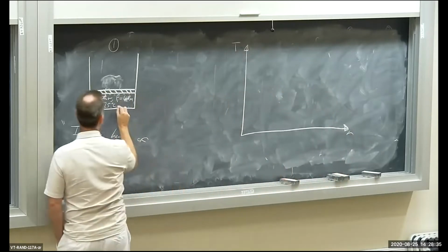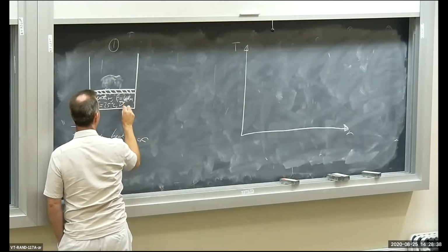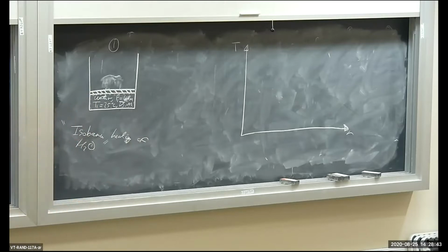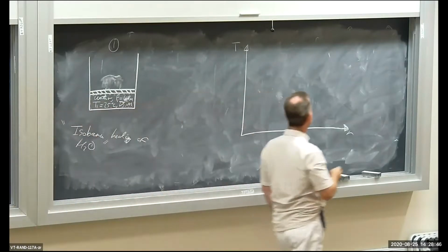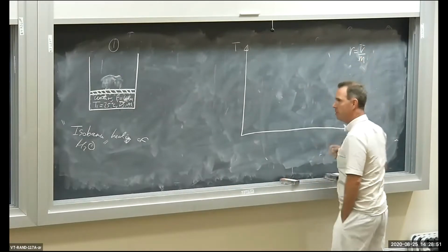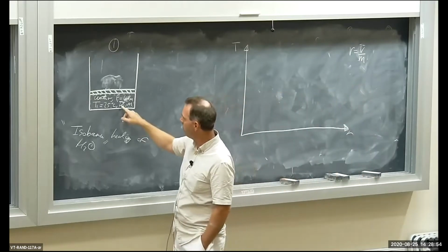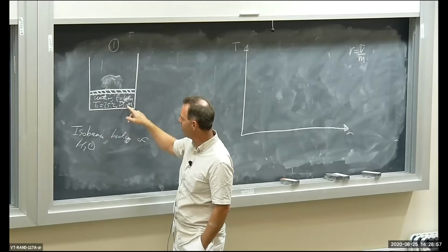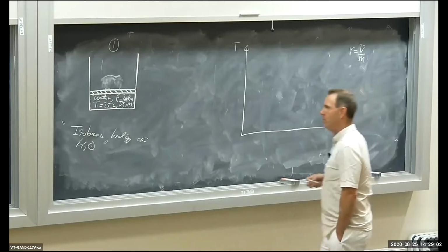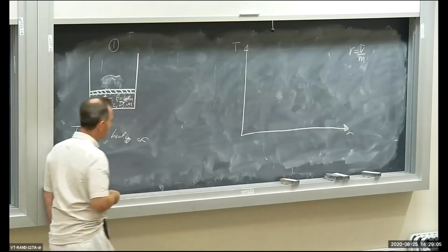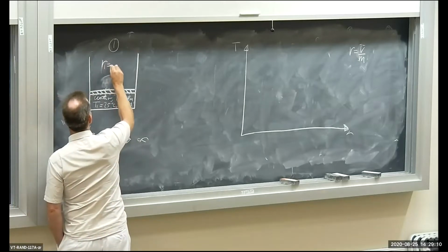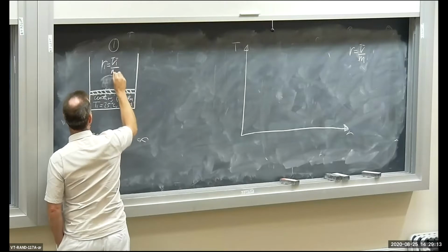So this thing originally has some volume V1 and a certain amount of mass inside. Remember, specific volume is volume divided by the mass of the system. So I have an initial volume, state 1 for my H2O, and there's a certain amount of H2O mass in my piston cylinder device. So specific volume at state 1 is equal to volume at state 1 divided by mass, okay?